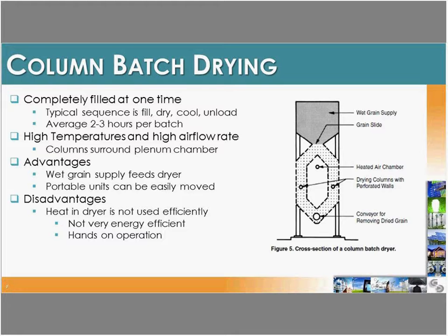Disadvantages is the heat in the dryer isn't really used very efficiently. So once it's in, it's out. It goes through the grain and it's done. So they say it's not very energy efficient. And it takes a lot of hands-on operation, which is the handling of the grain as well. Such as in the previous slide with the batch multi-layer, I should have touched on where before you can put your next layer in that multi-layer, you do have to monitor the moisture content of the grain to ensure that it's dried appropriately before the next comes in.